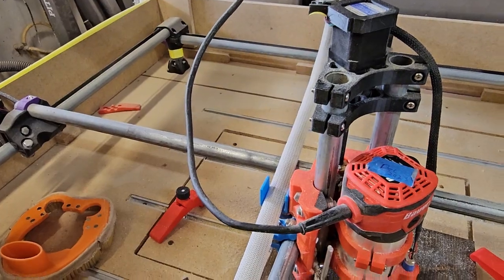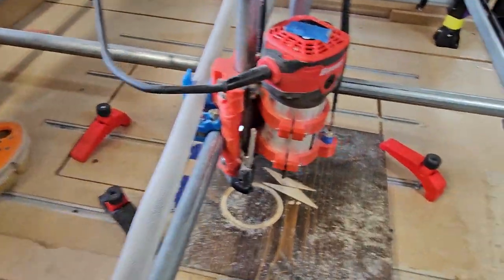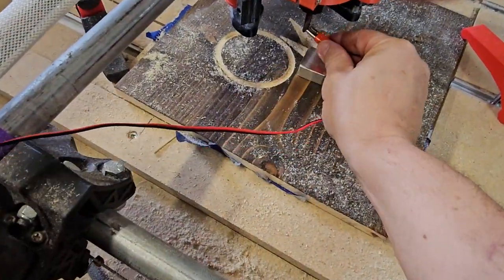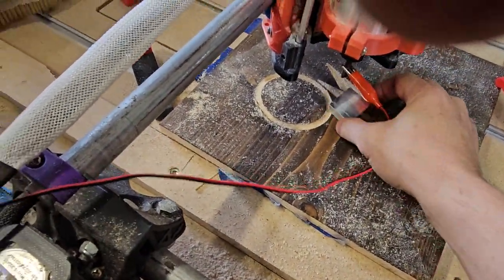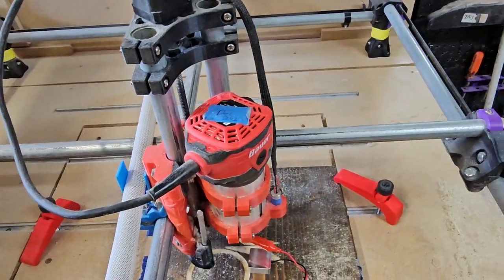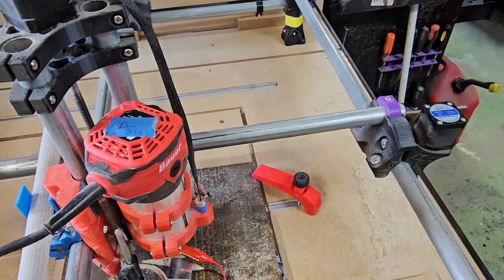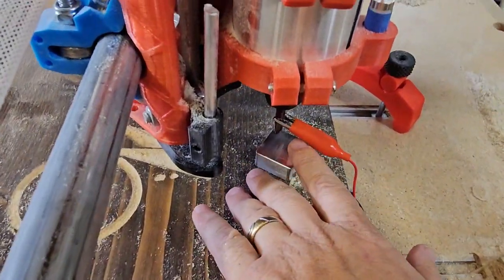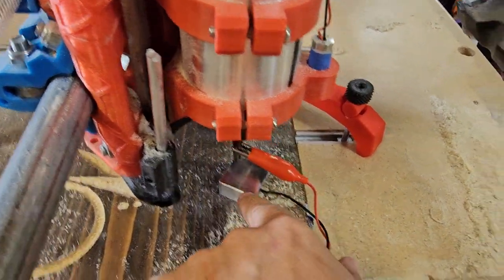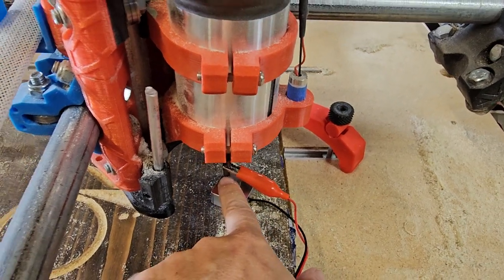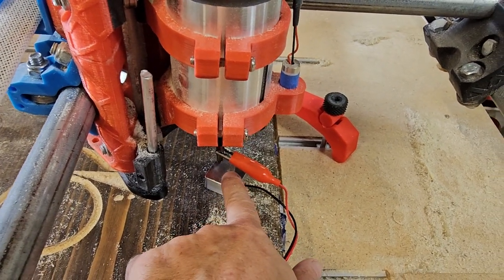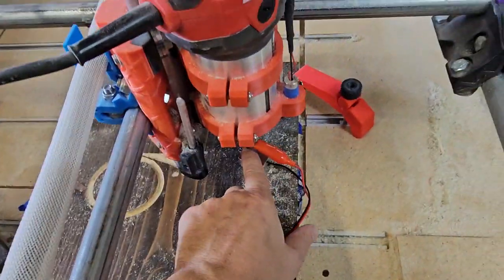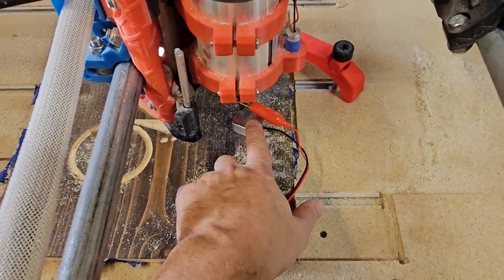I use a probe, which is this little piece of metal here. All this is doing, I'll move that down a little bit so that's on a flat spot. So all this is doing is you have to make sure you connect this, because this is completing a circuit. When I tell it to probe, it's going to come down here, it's going to touch this. This is wired all the way back to the board, obviously. And as soon as it touches, it knows that's where the surface is.